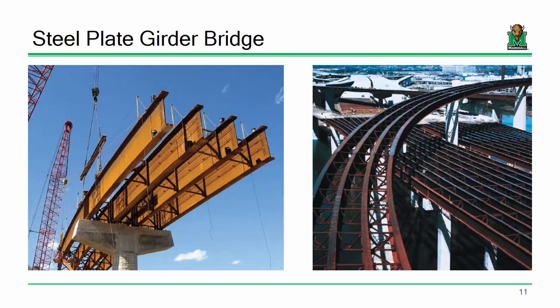Once the bridge is complete, it's not going anywhere. So it's kind of an interesting aspect that we have to consider. One of the things that we'll spend a fair amount of time on in this class is looking at a concept called constructability. Not because we have to answer the question, well, yeah, the bridge is safe to carry the truckloads and the vehicles, but can we safely even put it together? Can we safely erect it and construct it? That's an important point that we're going to need to consider.